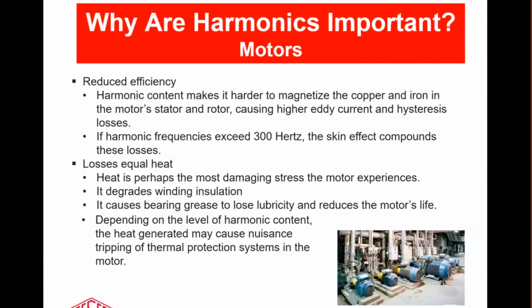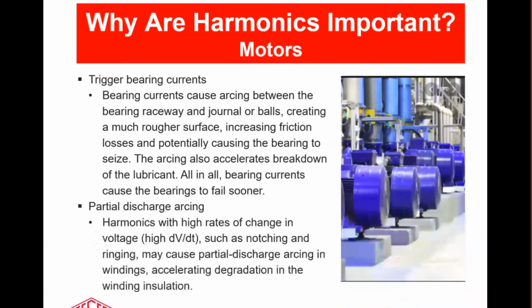And they produce stresses on the motor. They can degrade the winding insulation. They can cause greases and lubricants to lose their ability to lubricate. And depending on the level of harmonic content, because of these overloads, they can cause nuisance tripping of thermal protection systems in the motor.